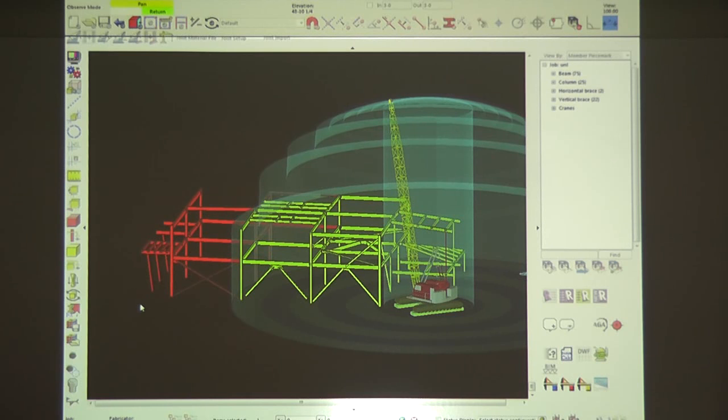So they're going to try to select a position that one crane can satisfy everything, or they're going to get a bigger crane, or they're going to have to plan in their schedule to reposition the crane. Because if steel's sitting there waiting on that crane, it's a lot of money, and vice versa. But basically, a lot of people don't understand that crane placement is very important to a project.